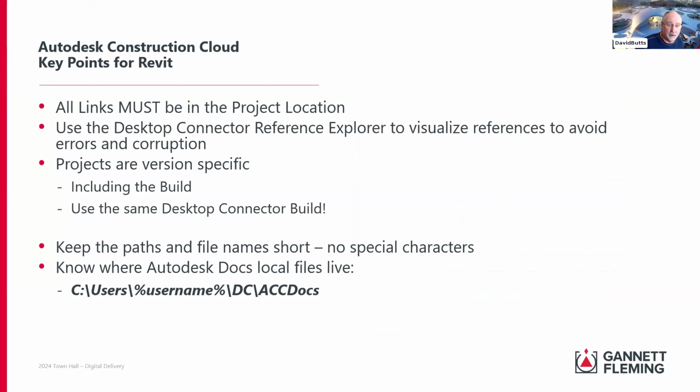And I actually wrote a blog post on my blog that I have online, the MEP CAD BIM engineer, mep-cad.blogspot.com. I wrote a post about this to tell people where you can and can't work and how you're supposed to work in ACC. And rule number one is any links that you have, whether they're DWGs, PDFs, images, point clouds, IFC files, anything, they have to live in ACC. You have to have those files in that climate.